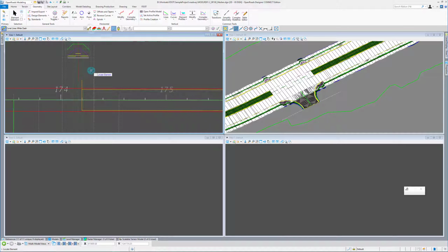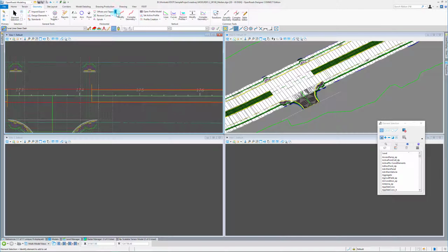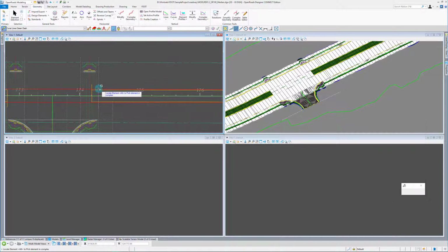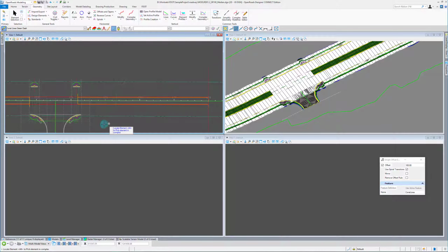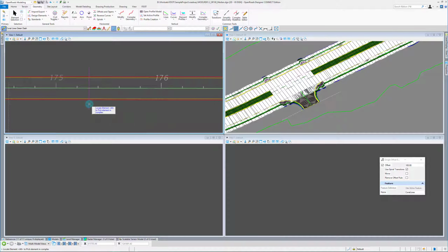And I'm going to go ahead and grab my, let's do green dash. I like green dash. So the minimum queue length for a 45-mile-an-hour road urban condition would be 100 feet. So let's set up our queue length. 100-foot queue length. And the L distance is 135. So that's the distance from the end of the queue length to the beginning of the taper. So we'll do 135.